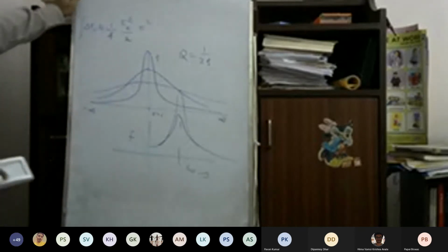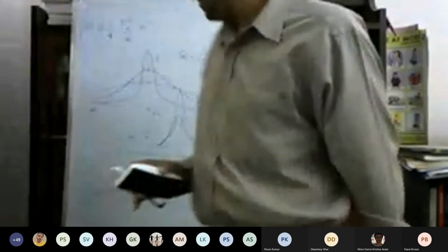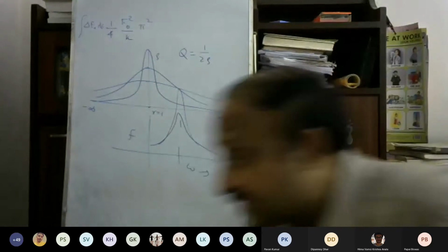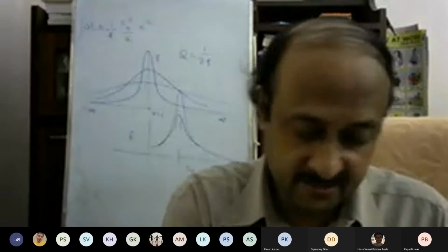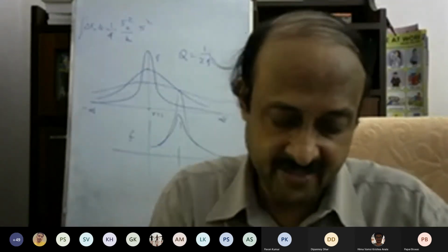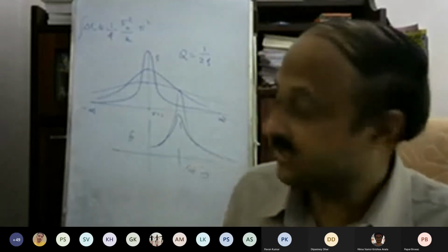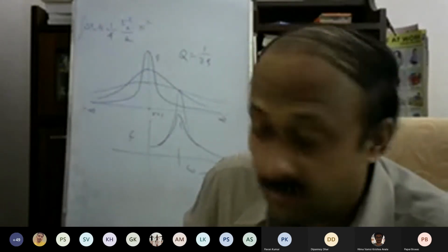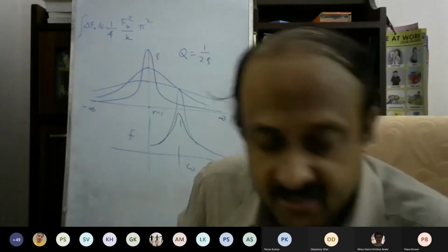I do not want to go any further today because we do not have anything left, I think, in this single degree of freedom system, excepting solving certain problems. But if you have not understood anything so far in today's class, then you may ask me. But quality factor is a very, very important concept in mechanical vibration that I am repeatedly telling you. Okay. Quality factor, you must know what it is, and quality factor is associated with the sharpness of the peak of the frequency response function of the system.